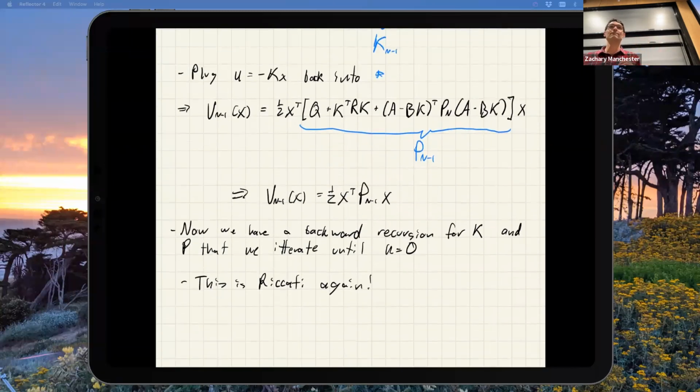It all depends on Q and R, like Q being positive semi-definite. Yeah, so as long as Q's, sorry? How do we choose those? Yeah, so that's what you get to pick. As an engineer, those Q and R values are what shape the behavior. That's what you get to choose. That's the cost function, right? That's what you're asking for.